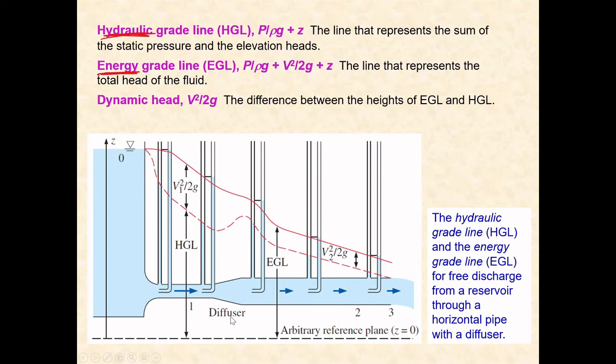So you have a diffuser here. A diffuser basically means going from a confined area to a greater area. The mass flow rate flowing through this pipe is the same. You can imagine that in a small diameter area the fluid will flow through faster, and in a large diameter area the fluid will flow through slower. As a result, you can expect high speed here and low speed in the larger area.